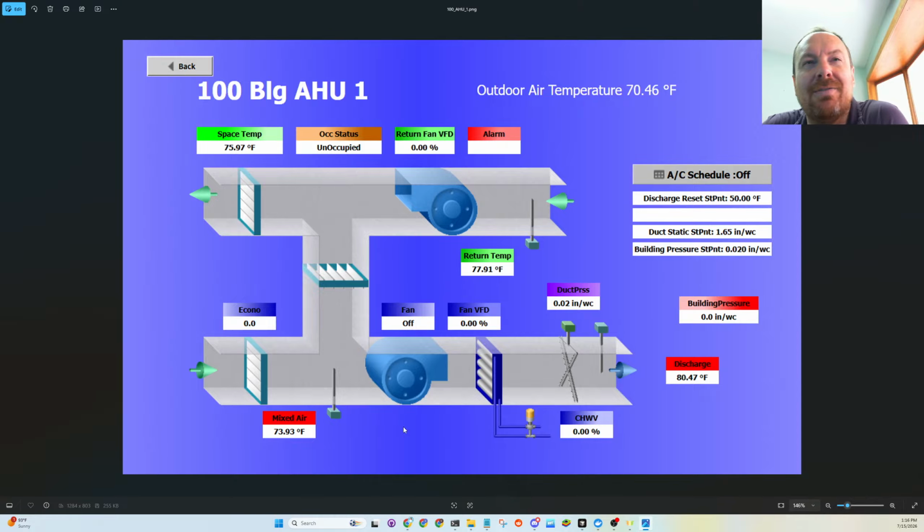For some reason, I only have 40 VAV boxes of data, which might not be very complete. So I'm not doing a complete VAV box level analysis. I think these are roof mounted air handling units, big guys up on the roof, just cooling coils, no heating coil. And I'm noticing in the data that there's no economizing at all.